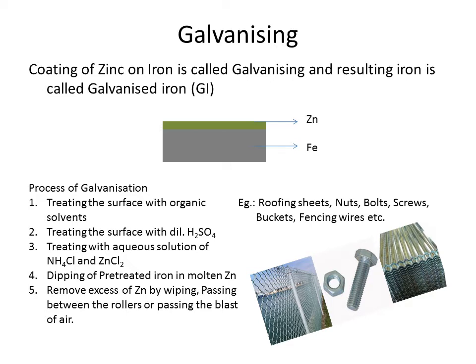Now we will discuss anodic metal coating in detail. Anodic metal coating is nothing but, to protect the base metal from undergoing corrosion, another metal layer will be deposited and that metal will be having lower electrode potential value than the base metal. So in that case, the coating metal will be anodic in nature, it will undergo corrosion, whereas your base metal remains unaffected.